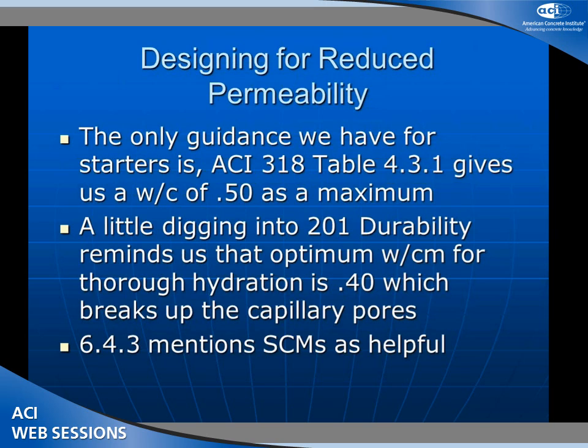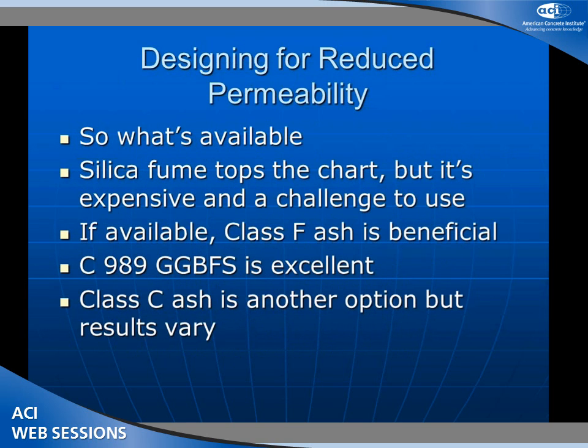See, 6.4.3 mentions SCMs is helpful. So that's it. I've been told now, okay, 0.40 is a good thing to be at, and the SCMs are helpful. So with that, let's look around and see what's available.